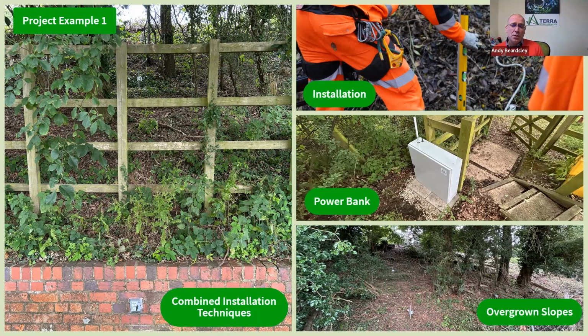So at this site, there are 220 metres of densely overgrown and wooded embankment to monitor. Minimal light vegetation clearance only was undertaken to facilitate the installation. There was one known track fault, but other instability evidence was observed along that 220 metres. There are 36 triaxial tilts installed, 24 clustered around the track fault location, and the remainder spread along the project area.